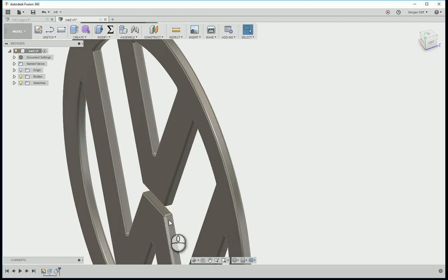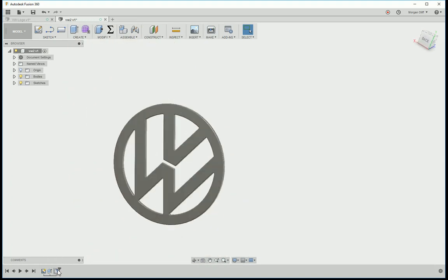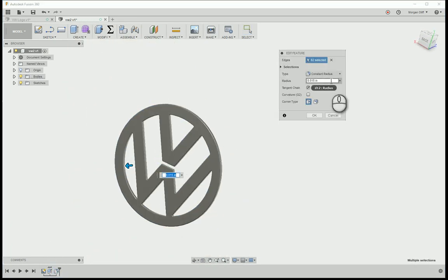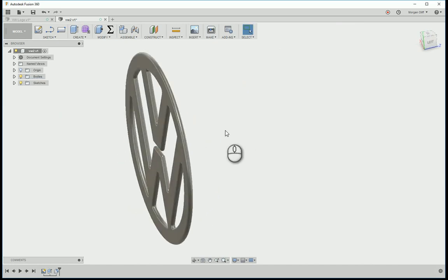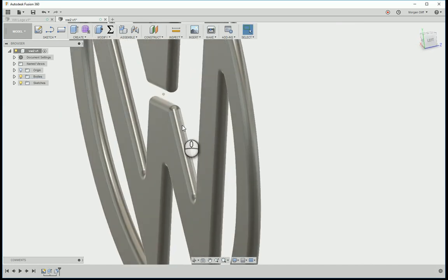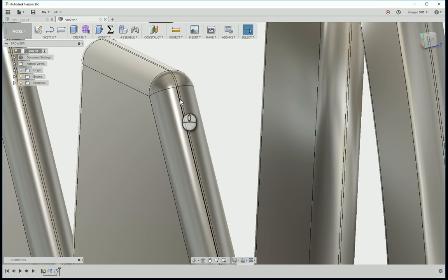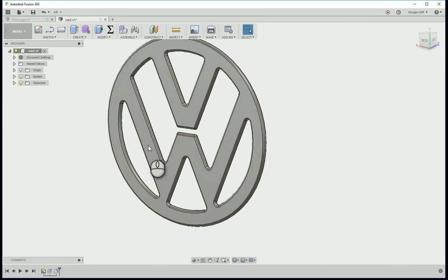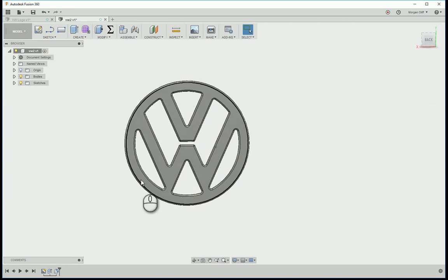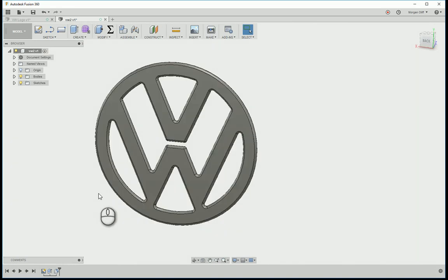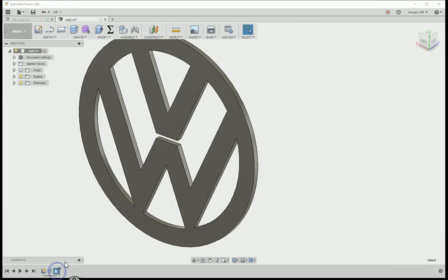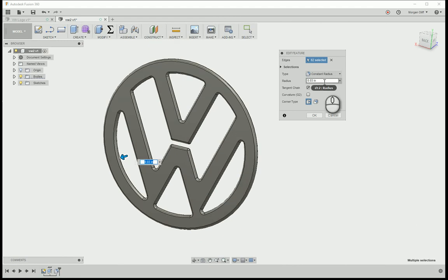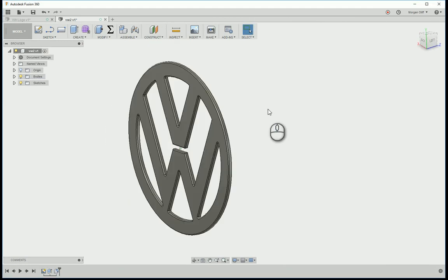That's half. So double was intersecting here, and it was not able to make that feature. Interestingly, 30 works because it almost turns it into a full round fillet there. See, there's only a small area. So maybe that's a case where you would want to make a parametric fillet. Yeah, 15 thou looks good.